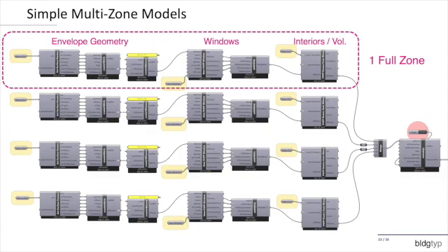You can either combine multiple thermal zones. So, different thermal zones that you might have in Energy Plus, you can combine lots of thermal zones, and then you can break them back apart and say, take these thermal zones, put them in one PHPP, take these thermal zones, put them in a different PHPP. And you can actually branch off multiple PHPPs from the single source, which is really helpful when it comes to things like mixed use buildings. You have a tower on a podium, you have different use types inside of your building, all of that kind of stuff can be pretty easily managed using these tools.